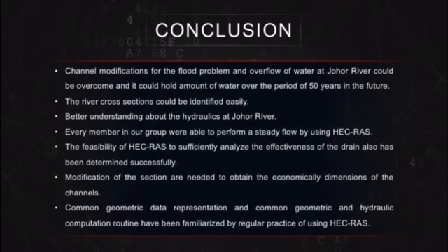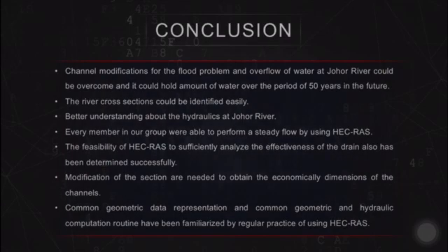So for the conclusion, the channel modification for the flood problem and overflow of water at Johor River could be overcome, and it could hold the amount of water over the period of 50 years in the future. The river cross-section could also be identified easily and give a better understanding of the hydraulics at Johor River. Common geometric data representation and common geometry and hydraulic computation routines have been familiarized by regular practice of using HEC-RAS.